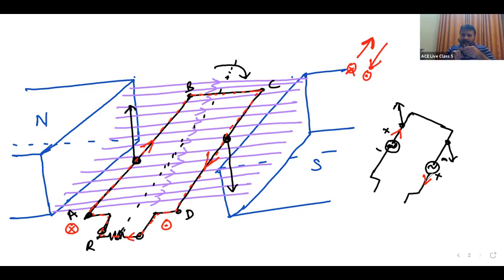When current is coming out from the positive terminal, it acts as a generator. If current is received at the positive terminal, it acts as a motor. If current is coming towards the positive terminal, it acts as a motor, absorbing electrical energy. But where current is delivered from the positive terminal, it is a generator. Here both are generating. These are the polarities. Current is leaving from the positive terminal here, and here also. Based on that, I am deciding the polarities: plus minus, minus plus.